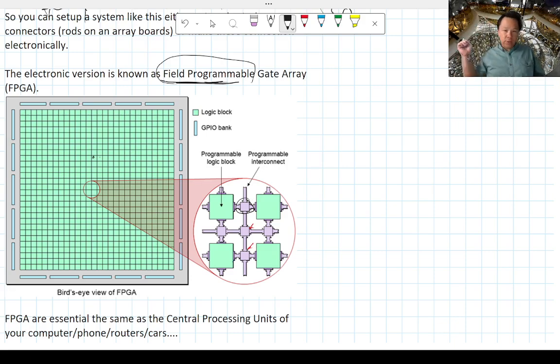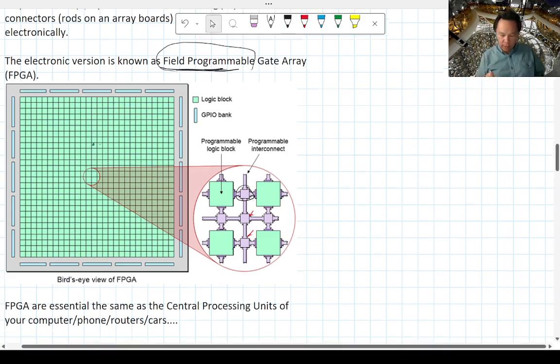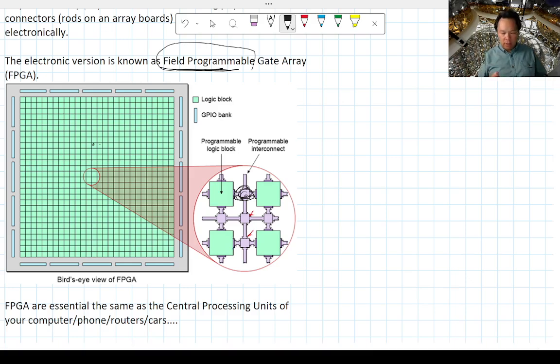So how do you do that? The way you do that in modern day electronics is by basically putting a little voltage. These are very low voltage transistors that you can program. If you turn on that transistor, remember that basically makes the collector to emitter conductive. So if you can make this little point here conductive or not, that changes how these cells are connected together.